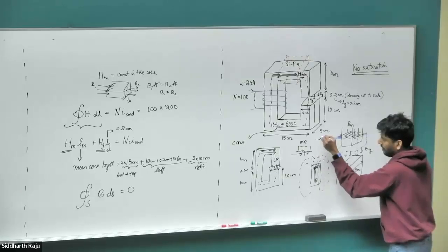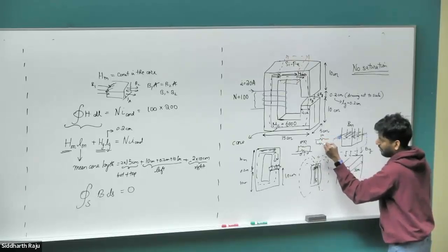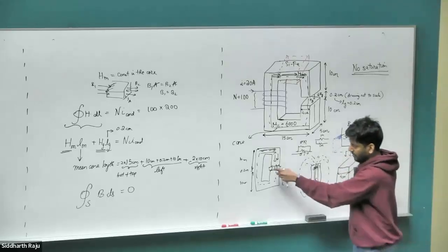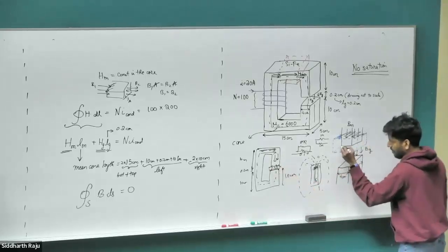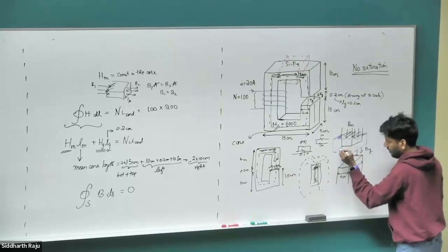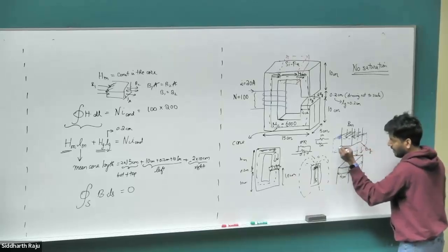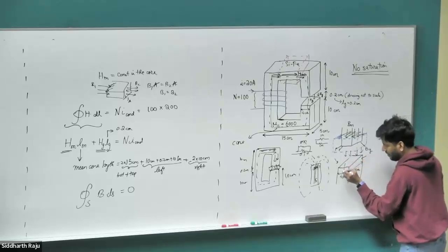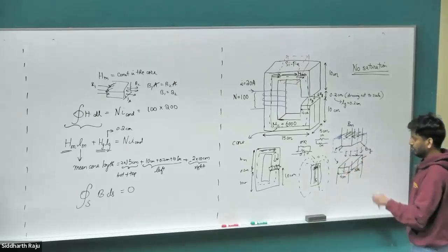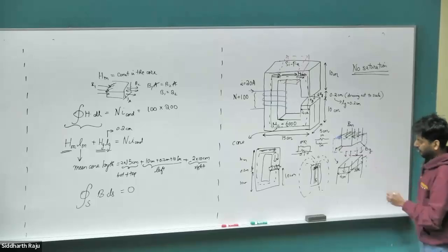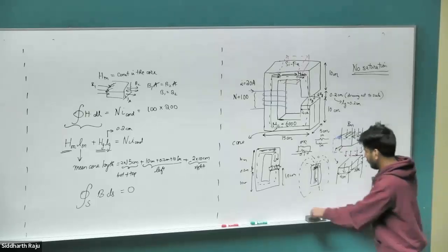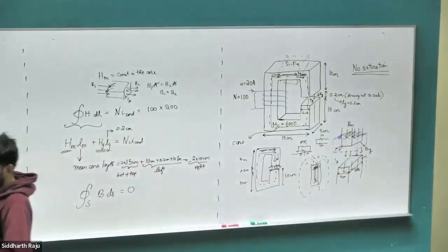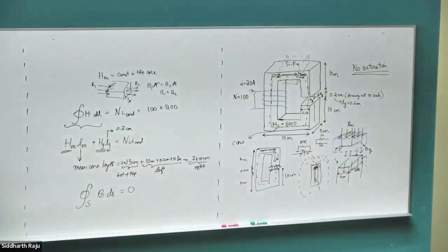So it's like 1 megaohm resistance in parallel with 1 megaohm resistance. It's going to go through both pathways equally. So that's what happens once it hits the air gap. So the B field is not going to be constrained just in this vertical direction. It's going to spread around, and this is called fringing. And then it's going to spread back in, and once it encounters iron, again it has a preference to go through the iron instead of choosing to go outside of the iron. Okay, so this is fringing. If we ignore fringing, you can use the formula A_c equal to, yep, Thomas.